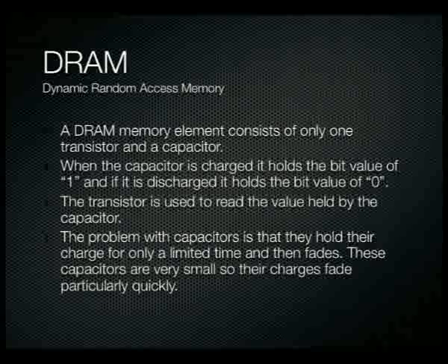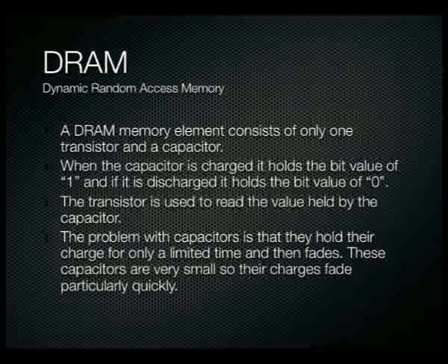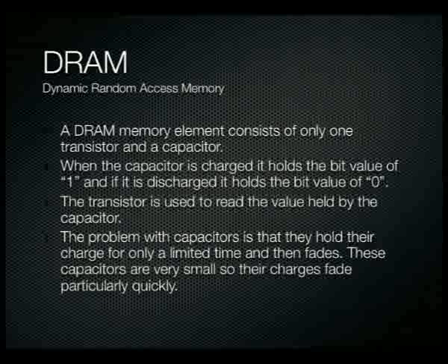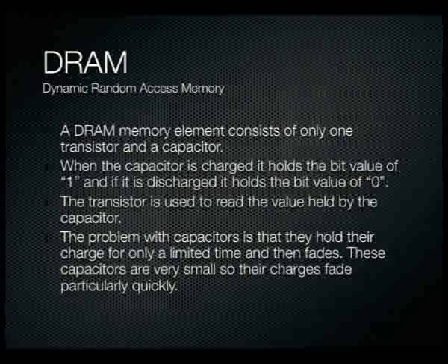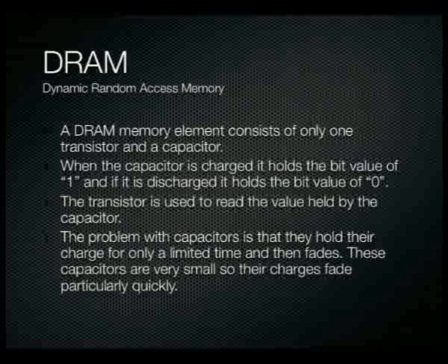So the problem with the capacitors is that they hold their charge for only a limited amount of time. When we're talking about capacitors inside a memory element, these are going to be extremely small capacitors, so they are going to fade extremely quickly. They're going to be pretty much gone if we don't refresh them. So that's why we've got to constantly keep refreshing the memory elements, to keep sampling each memory element and then recharging those capacitors so we can maintain that bit value. If your memory contains the bit values of 0, then you really don't have to refresh it. But if it's a value of 1 anywhere in those bit values, you've got to refresh them, because if you don't, they're all eventually going to end up representing 0 in value, and you don't really want that.